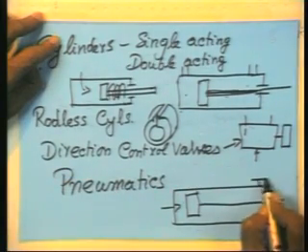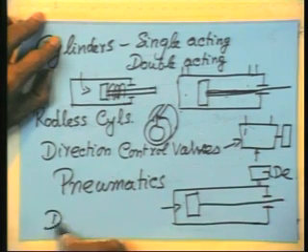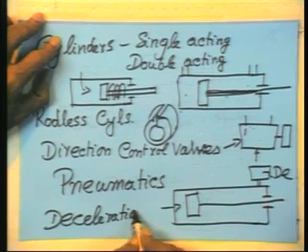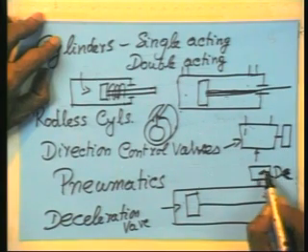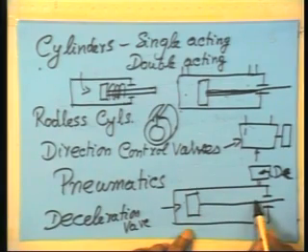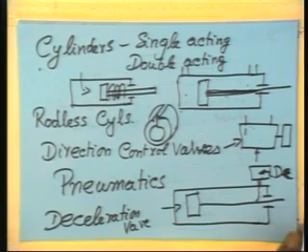Usually they put what is known as a deceleration valve here. This is what it is. The air on this side, you control the rate at which it is exiting and consequently decelerate the piston. Instead of going and banging, decelerate.